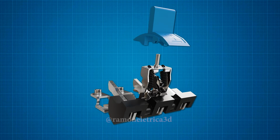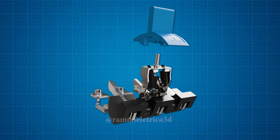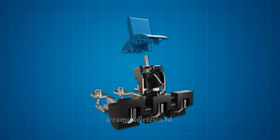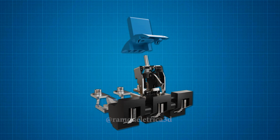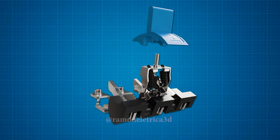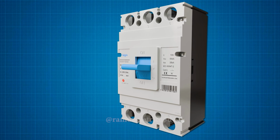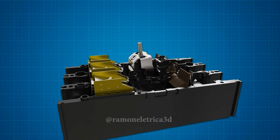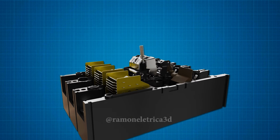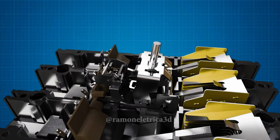Now that you've seen how the handle components move, it's easier to understand how the MCCB turns the circuit on and off. Earlier, I showed you that one of the differences between an MCCB and a miniature circuit breaker, MCB, is exactly this handle mechanism. While an MCB has only 2 positions, the MCCB has 3, and the center position is where the breaker stays when it trips due to a short circuit or overload. So let's understand how the handle stays in this center position.